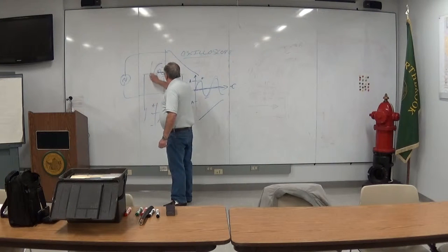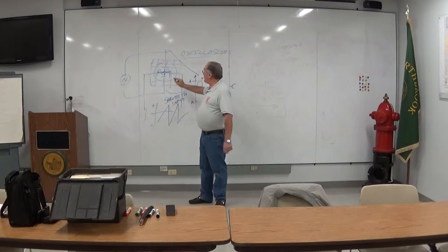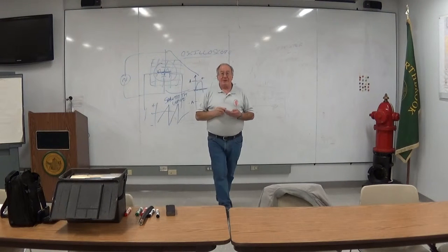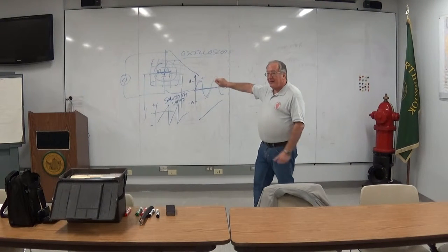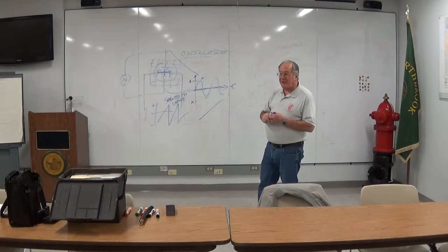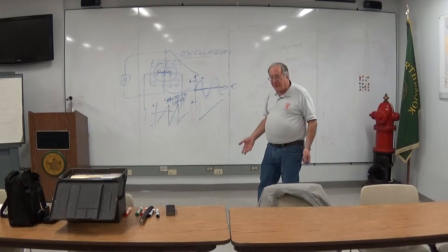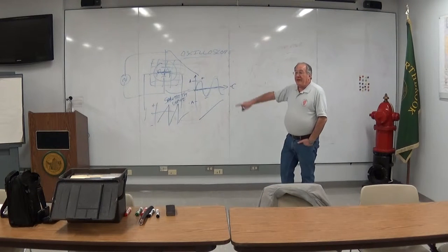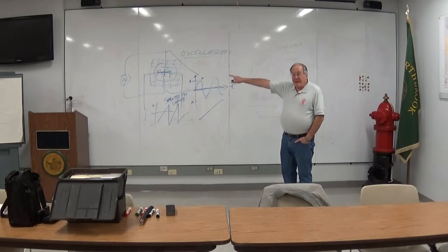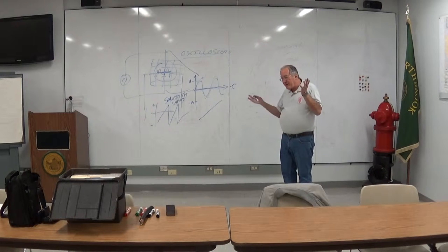And then we put a little grid on this scope. I'm putting a lot of lines here, I know that, but if they put this thing called a reticle in front of it, you can actually count the centimeter squares and say, okay, according to the amplifier in that oscilloscope, each centimeter represents so many millivolts or microvolts or actual volts. And you can measure that voltage. You can measure the peak, and you can measure the shape, or you can look at the shape.